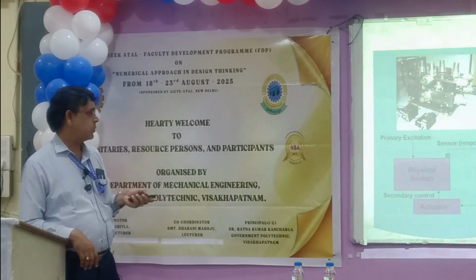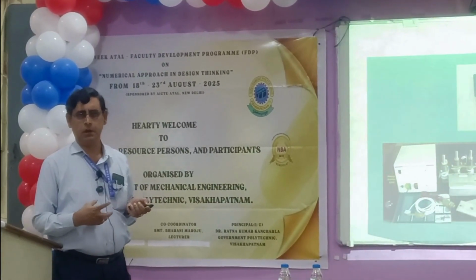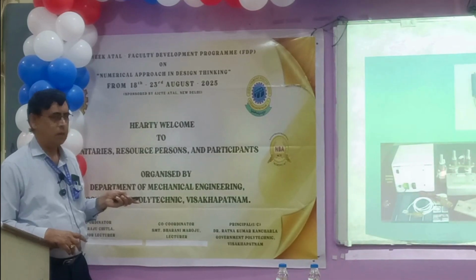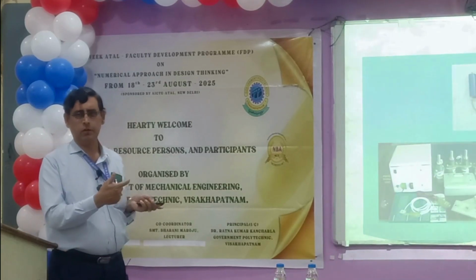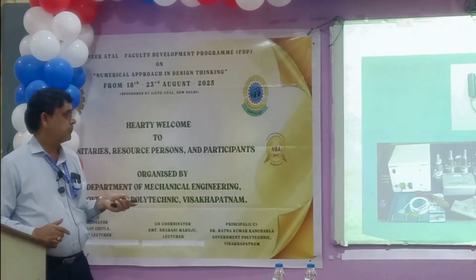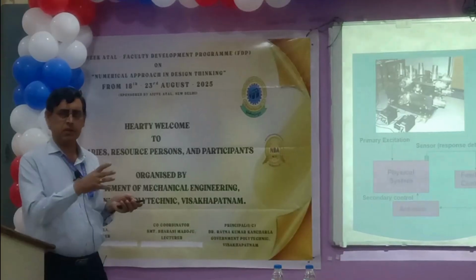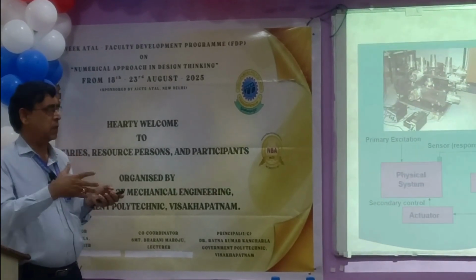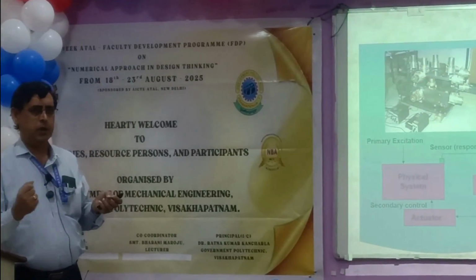Whereas the previous one that I showed, this magneto-rheological mount, is basically semi-active. It's not fully active actually. That is why you can see some kind of rubber also here, like rubber mounts. It is a combination of rubber mounts and active control. That's why we call it semi-active control. Whereas here it is a fully active control. That means you are actually using actuators to control the noise, with destructive interference. Whereas the engine is producing noise, to control it you are putting actuators all around and creating anti-noise.